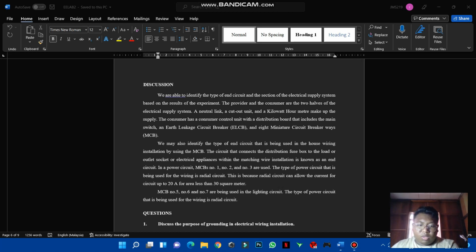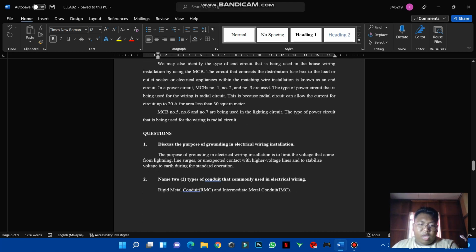Next we will go to the questions. We have two questions. First, we need to discuss the purpose of grounding in electrical wiring installation. The answer is that the purpose of grounding in electrical wiring installation is to limit the voltage that comes from lightning, line surge or unexpected contact with higher voltage lines, and to stabilize voltage to earth during standard operation. And number 2, we need to name two types of conduit that are commonly used in electrical wiring.